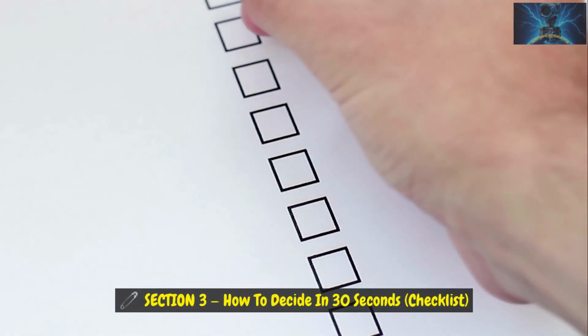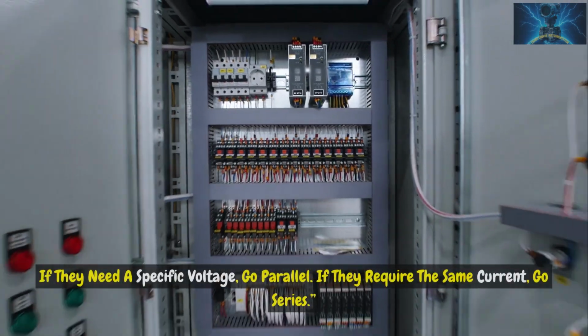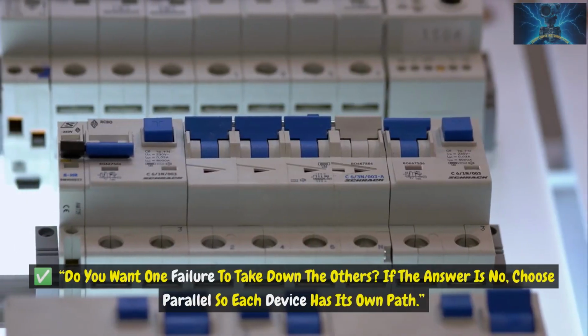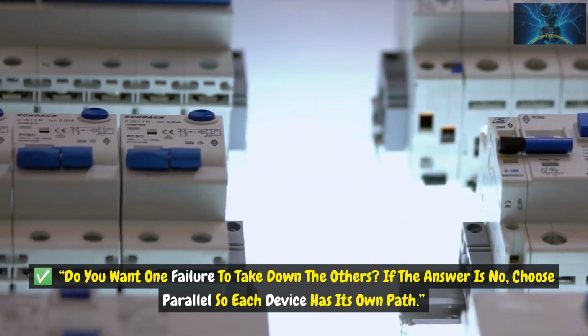Section 3. How to decide in 30 seconds. Checklist. What do the devices require? If they need a specific voltage, go parallel. If they require the same current, go series. Do you want one failure to take down the others? If the answer is no, choose parallel so each device has its own path.